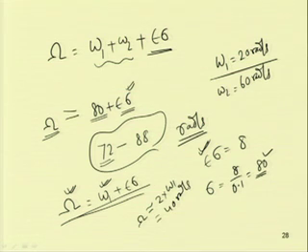So, we may have subharmonic resonance, and when it is equal to 10 radian per second, we may have the other type of resonance condition. That means, when it is away from the natural frequency, that is away from this 60, we can also have resonance condition. So, in the case of a nonlinear system, we can have superharmonic and subharmonic resonance conditions.